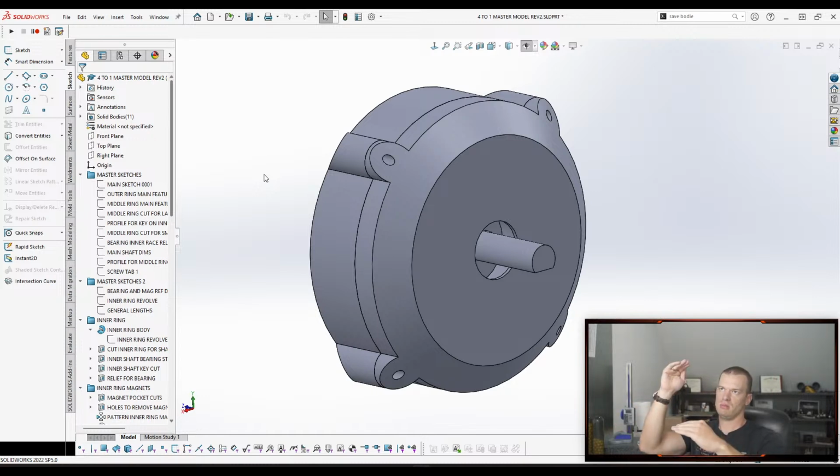So maybe you're doing a combination of the two. You have the skeleton sketch, you have this master model which has a lot of your organic geometry in it, and then you have your derived parts, and you're inserting your organic features into your other parts to do your detailing work. So that might be an interesting use case for it.